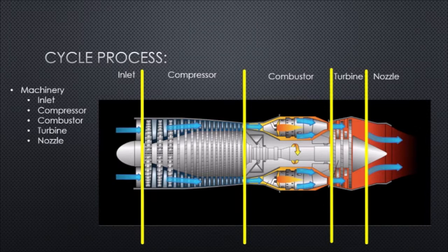Now the cycle in a jet engine is accomplished through the use of rotating machinery that operates much like a fan. Each fan, or disc as we call them, has blades on it that are essentially very similar to wings. These blades draw the flow deeper into the core. The first set of blades that the flow meets inside of the core is called the compressor. These compressor blades are lined up one after another and get smaller and smaller to compress the